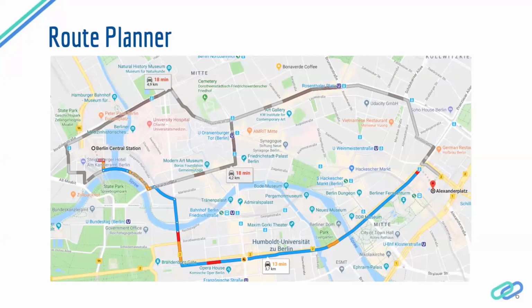Generally for route planning, we need better maps. So we use HD maps. HD maps are maps which, along with the route information, also have further information like where the traffic signs are, where the objects around are, where the lane markings are, and what the different types of lane markings are, like dashed lines or continuous lines. They also have information on whether there is a bicycle path beside the road, and the static objects in the environment like footpaths, curbs, etc. This information will also help in localization to understand where the car is.